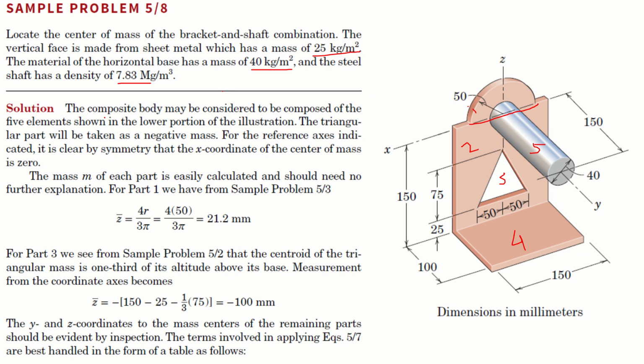This is the density. Now you can take this information and we can find the value of these plates along the z-axis. If you look at this, he has placed the heaviest position at the origin, that is the cylinder. With this we can simplify a lot of things. Number one, since all the symmetric axes lie along the z-axis and y-axis, the x-axis is eliminated naturally. So the location of the origin of coordinates is also very important.